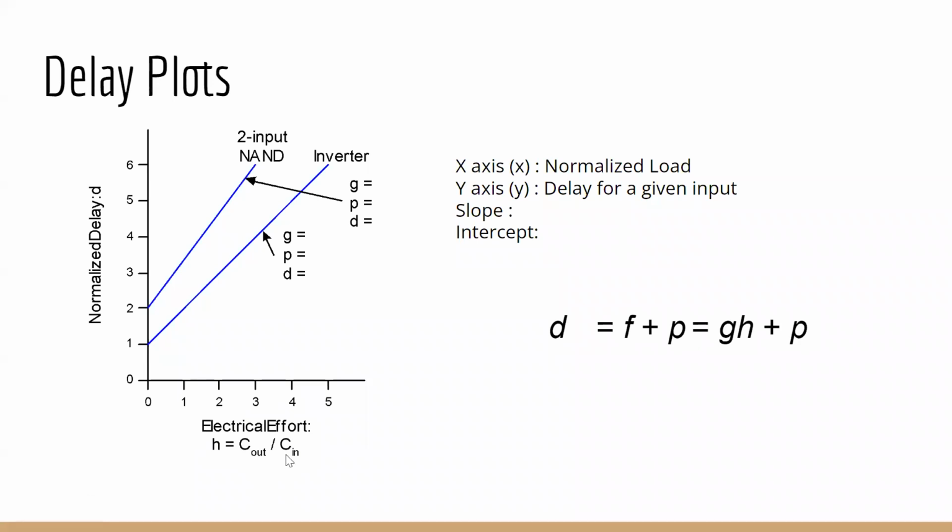So here, the value when this h is 0 is basically the parasitic delay. The parasitic capacitance coming from the self-loading of the gate, multiplied by the resistance of the transistor, is this delay. And whatever is additional over and above this is coming from the straight line, which has some slope. Okay. So this is coming from the load component. This is the self delay of the gate. Does that answer your question?